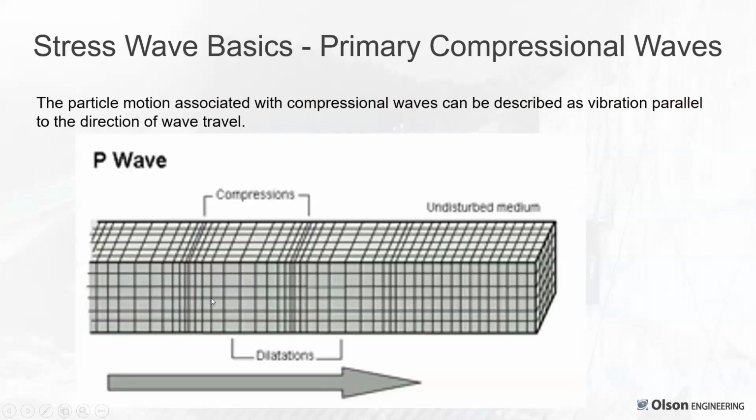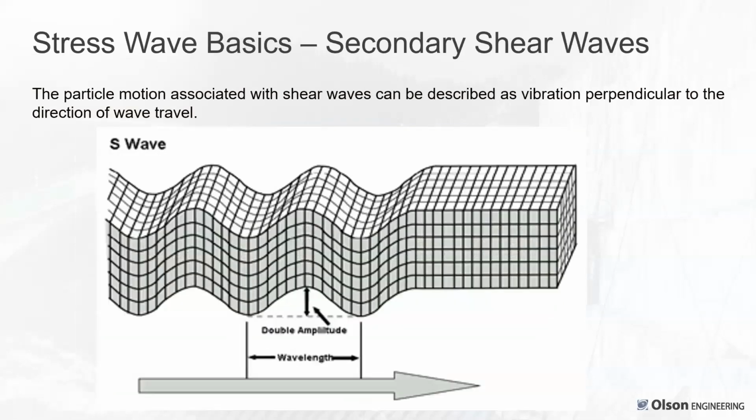To visualize this, a compressional wave, as it propagates, will compress and extend the medium as it passes through. A kind of push-pull action. The shear wave, you could think of like an earthquake fault shearing; it has a shearing component. We primarily use shear waves in earlier work. Dr. Ryan North and Travis Nielsen with our company gave a webinar that's also on the YouTube site on seismic testing, and we use shear waves in seismic testing for getting the shear modulus as well as related Young's moduli.